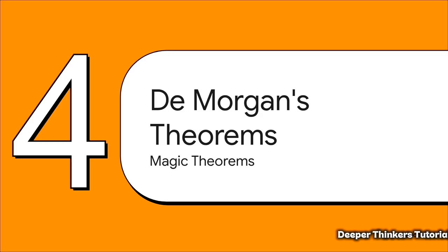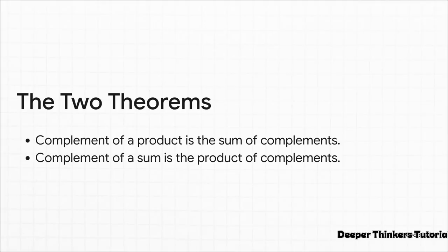Section 4, we have the law of complement, which is under De Morgan's theorem. You discover that the complement of the product is the sum of the complements. This is not rocket science, it's not very difficult. It means that when you take the product of two inputs like A dot B and put a long complement on top of it, it is still equal to A complement plus B complement. So it's just like when you break that long complement on A dot B, that's A and B.